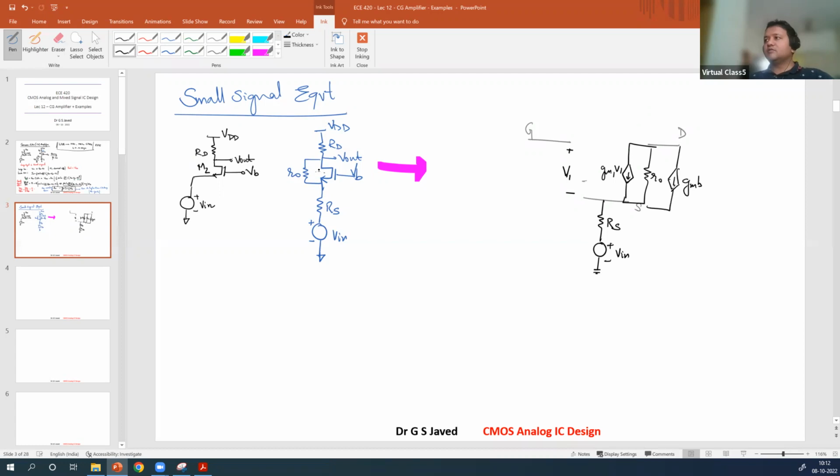Now what is the voltage supply here? Bulk to source, so VSB. Finally you have the RD resistance connected to the load. This is your V out. So this is current ID. This is IL, and you know IL is minus ID, if you apply KCL here. Right now, what are the things that you have to apply? So what is the supply voltage applied at the gate here? VB. Remember, this is the other connection that you have.